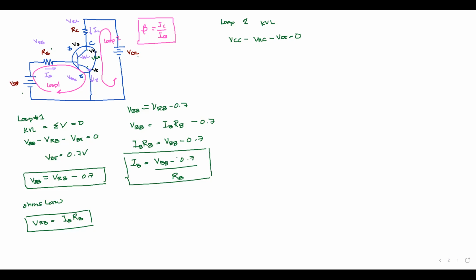So, as I told you on Monday, the diode's voltage drop, the voltage it uses, is basically equal to 0.7 volts. So it follows there. It is 0.7 volts. Okay? So now we have this one. Here, we could now say that V RC is equal to I sub C R sub C.